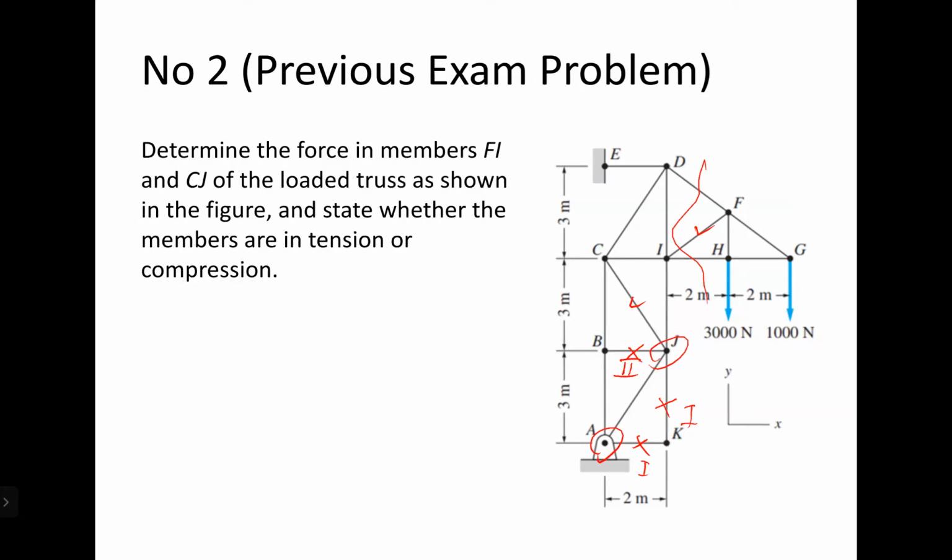Or the other thing that you can do, once again without determining whether BJ, JK, and AK are zero force members: besides cutting here, this is the first cut, then you can solve it using a double cut like this. This one can solve the problem as well. Okay, Omar?